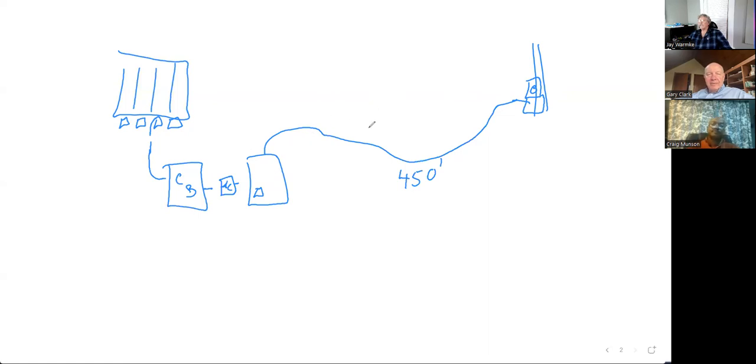In our situation, we ended up going with 2-aught wire, buried there, which was a royal pain to install. Imagine digging a trench for that. Well, it wasn't so much the trench, but it was pulling it through the conduit.